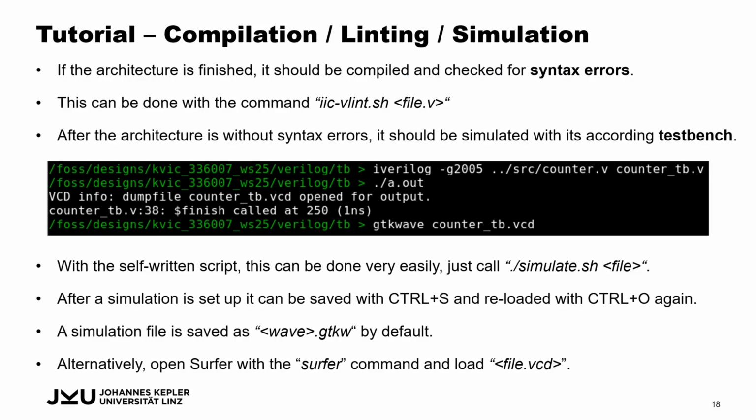If your Verilog entity or module or architecture is finished, it should be compiled and checked for syntax errors, and not only for errors but also for warnings. In chip design, this is crucial. I mean, I sometimes ignore warnings. I think everyone has done this once in their lifetime, to ignore a warning, but you still can ignore the warning, but you have to understand it. This is the difference here.